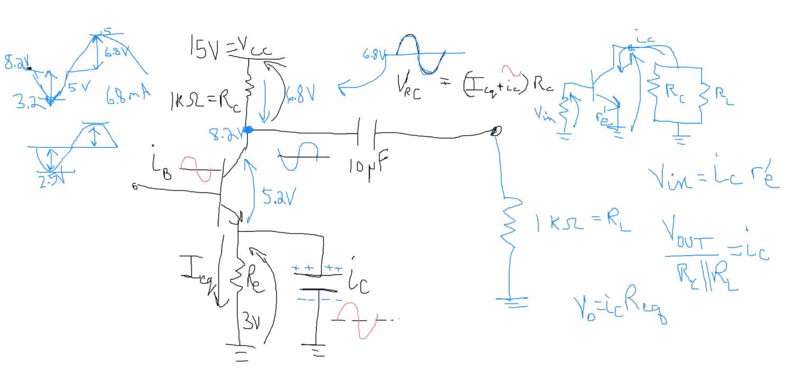And in the textbooks, they like to call that little RC. The little RC includes the load. So little RC is going to be divided by Vin, which we have the equation for above. That's just IC times this effective resistance at the emitter.